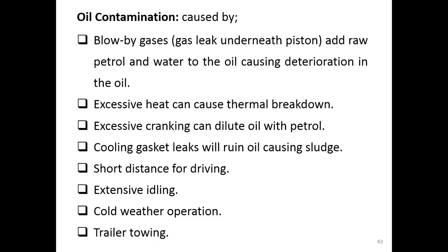These are the causes of the extra amount of heat. When it happens, it can cause thermal breakdown of our oil. Also, high engine speed or excessive cranking, or running the engine at high speed for a long time, can dilute the oil with the fuel.